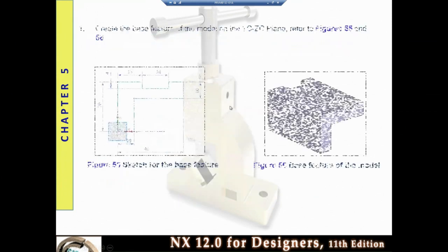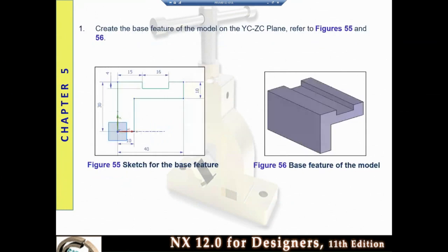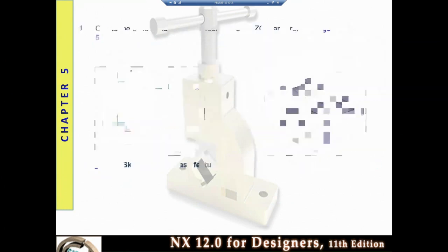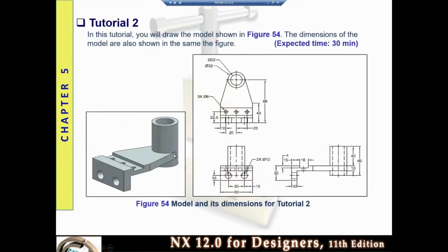And let me go back. Yeah. So once you create that one, then you need to do another extrude of this one. So basically you can either create a new plane on the top or a sketch on here and then do a kind of two direction extrude. So both of them are fine. Of course, it's better to create a plane because you're basically practicing what we've done today. And then make sure for all of them you use the unite boolean. Once you do that, these are really simple holes that you need to create on the surfaces.